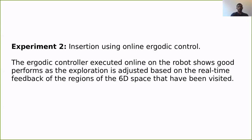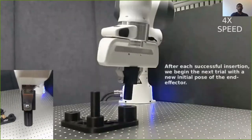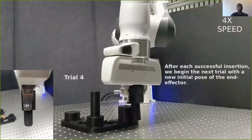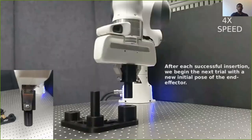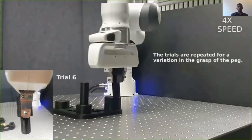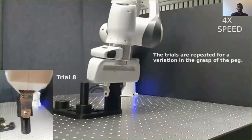Finally, we implement ergodic control in a closed loop manner on the real robot. This achieves optimal ergodic exploration for insertion as it considers the history of the state of the end effector. With the closed loop ergodic control implementation, we observe that it achieves a 100% success rate and takes less time for insertion compared to the other methods. The approach can also accommodate uncertainties in the grasp of the peg, as the human demonstration included different grasps for insertion.